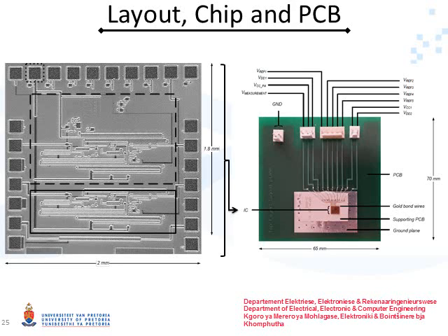Because of layout restrictions, there is only one bond pad to provide the bias voltage for both the non-linear and linear power amplifiers. The bond pad restrictions were laid out by the RF probe interfacing and wire bonding requirements. It was recommended that the RF signal and DC bond pads be separated for the following reasons.